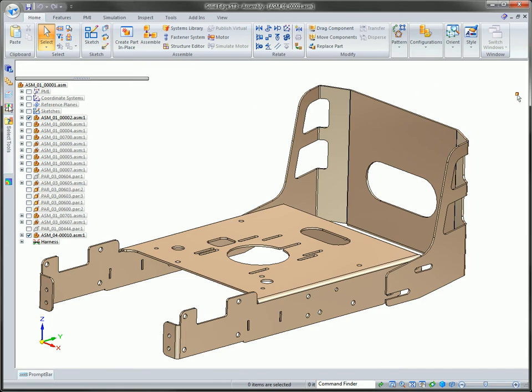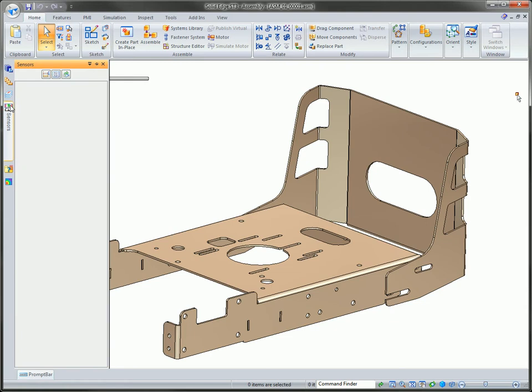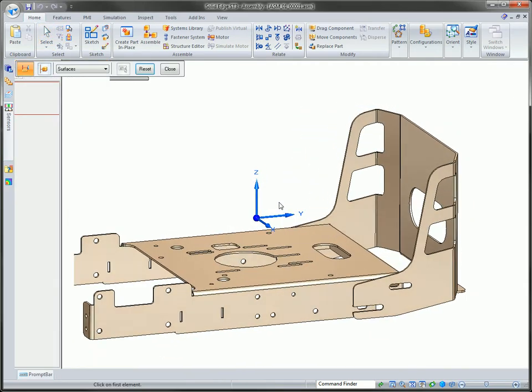But for sensors, design sensors inside of Solid Edge, these are tools that constantly monitor your design intent. And in doing that, we have some tools inside of assembly that will monitor distance, monitor a dimension or a weight, or any kind of property that inside of the variable table can be placed in there. And we also have some custom sensors that we'll get to in a second.